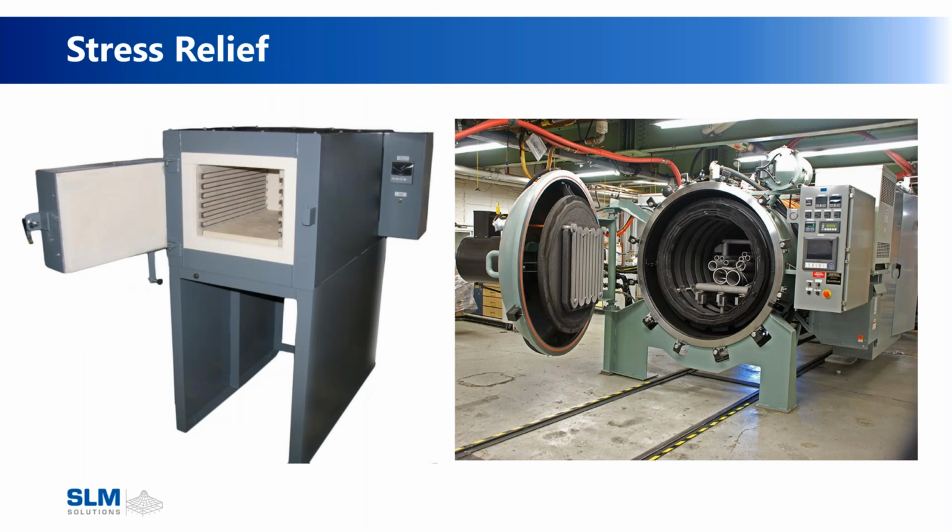After that, stress relief. So we see two different types of stress relief furnaces here. Again, this is a welding process. Even parts as low stress as aluminum tend to warp as we cut them off the plate. So if you're just doing a simple stress relief, a furnace on the left-hand side with an argon blanket may do just fine.